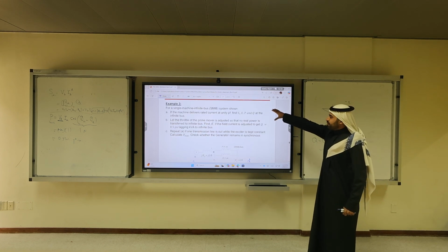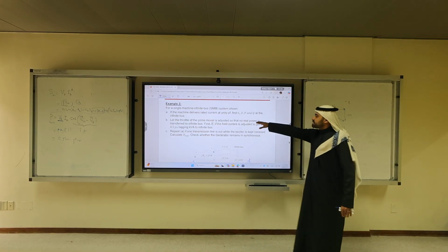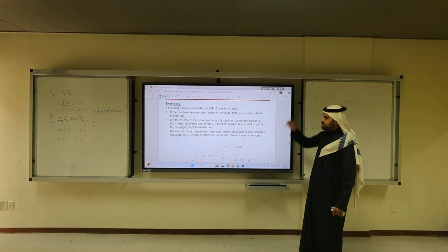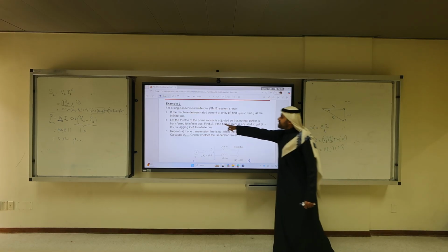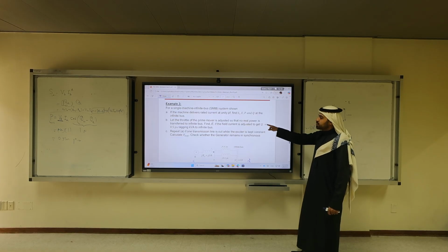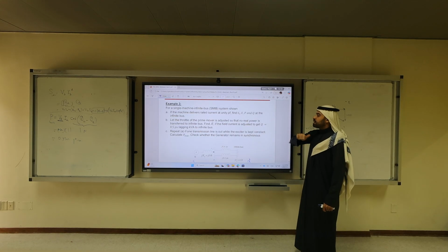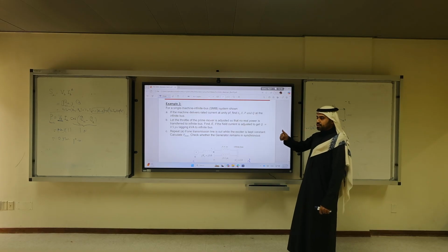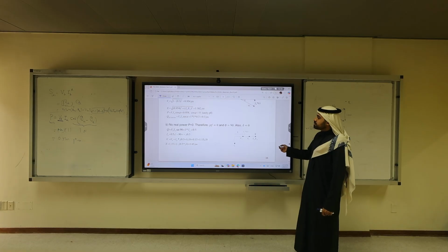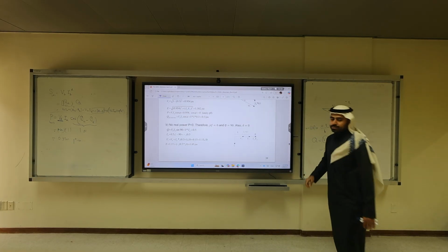So at the infinite bus, he's telling you that the prime mover is adjusted such that the real power P is 0. Find the new excitation voltage if the field current is adjusted to get Q to be 0.5. It was 0.3. Now it is 0.5. How to solve this problem? If the real power is 0, what does this imply?